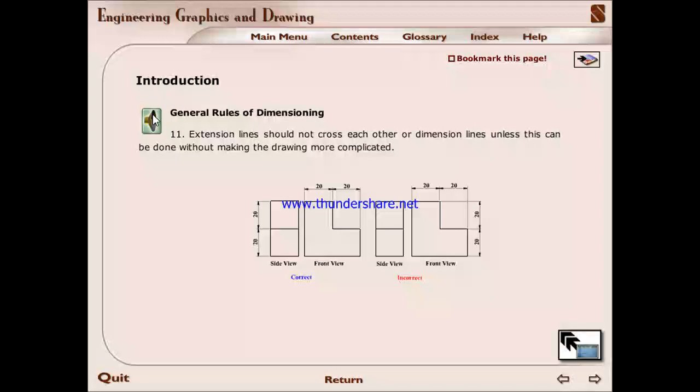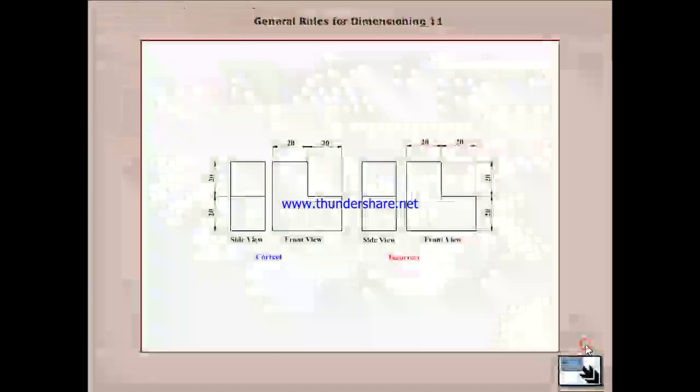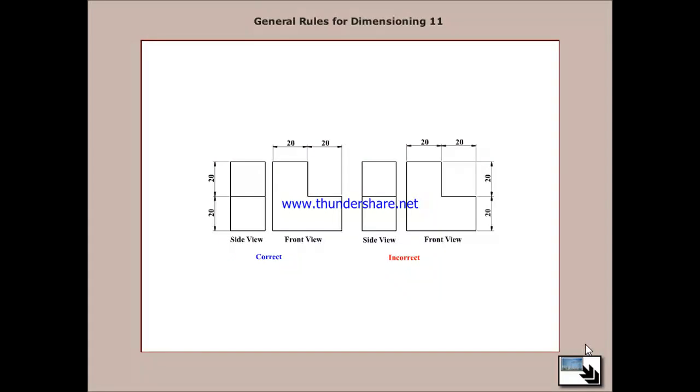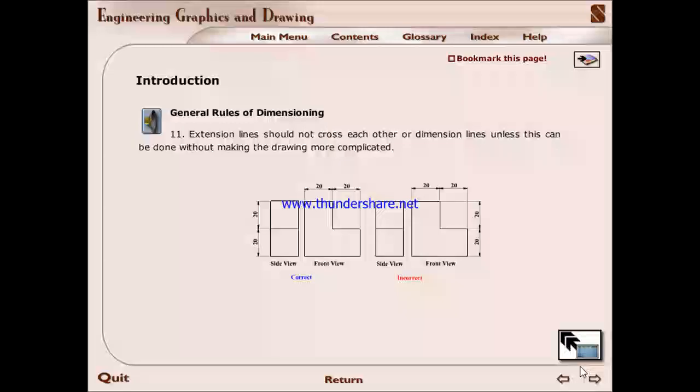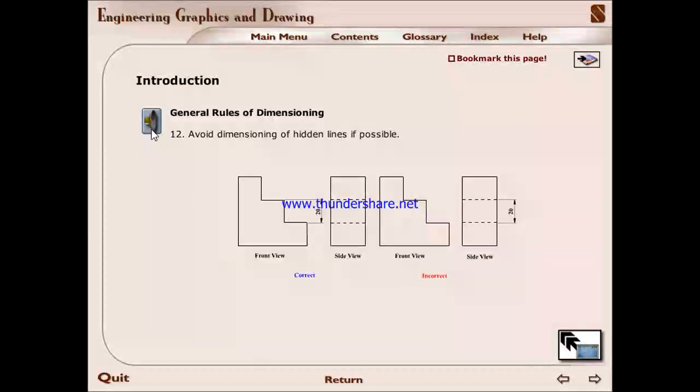Extension lines should not cross each other or dimension lines unless this can be done without making the drawing more complicated. Avoid dimensioning hidden lines if possible.